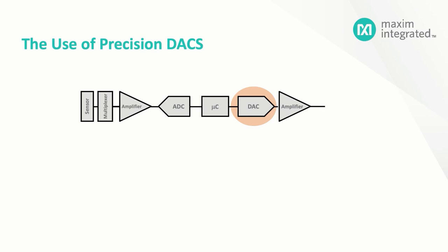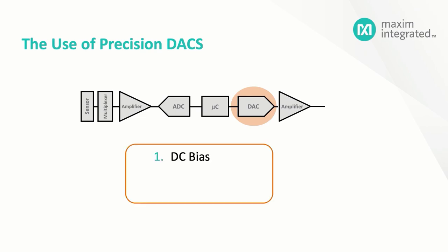Consider some typical use cases for a digital to analog converter. First, let's think about the case in which the DAC is used to generate a DC bias voltage. Maybe you need to bias an AC signal into the sweet spot of a detector, or maybe null out an interfering DC signal. In such a case, resolution and stability are going to be the most important factors. Speed? Not so much. The bias voltage likely changes really slowly. But what if the DAC is directly generating a modulated radio frequency signal? Well, now, it's all about speed, and I'll filter any noise artifacts out in the analog world.